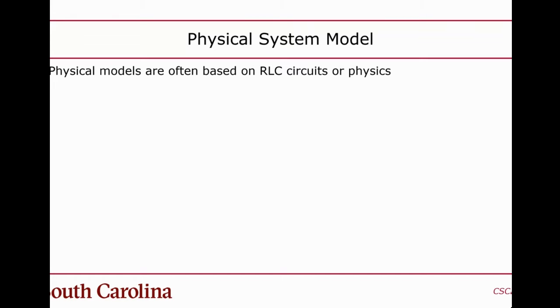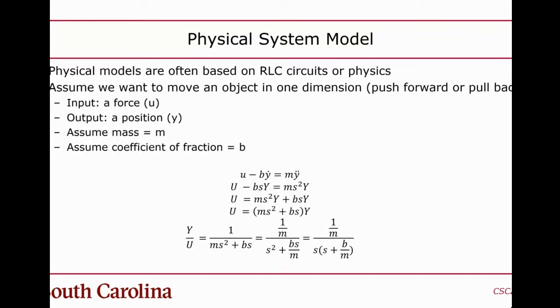There is another way, though. You can also use a data-driven approach, where you measure the response of the system by injecting different types of sinusoids into it, and then you can build the transfer function from that as well. That's called system identification. So there are two approaches. We're not going to talk about system identification in this class. I'm just going to show you the first principles based approach, where you build it from first principles. Let me give you a really simple example.